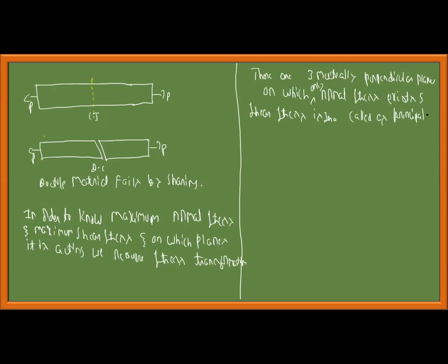Principal planes are principal stress. Upon principal plane, principal stress acts. There are three mutually perpendicular planes on which only normal stress exists and shear stress is zero.